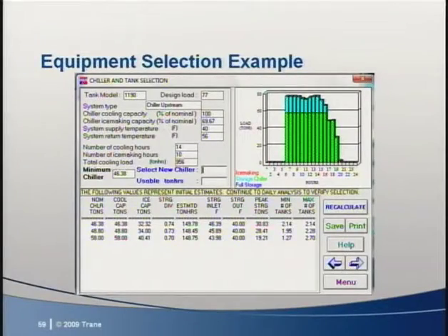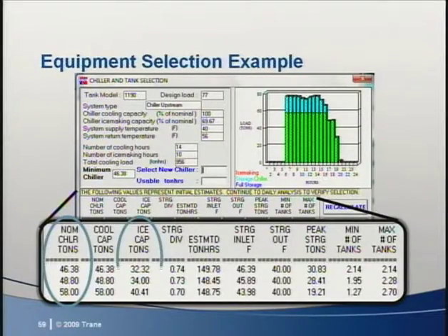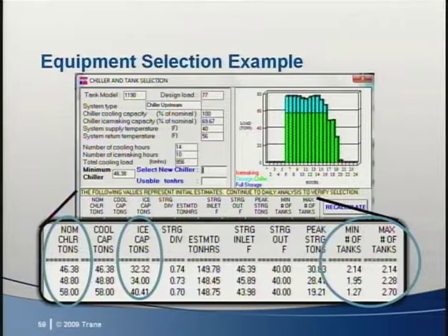As you would expect with a larger chiller, the minimum number of tanks is lower and the maximum is larger. On a day when charging begins with empty tanks and using the time available, the third tank is filled up to 70%. If we choose to invest in 3 tanks, energy savings will be increased by demand limiting the chiller operation during the day. If lower first costs are desired, the 2-tank option will work, and it can complete a charge in less time, providing operational flexibility. That does not preclude a 3rd tank from being added in the future.